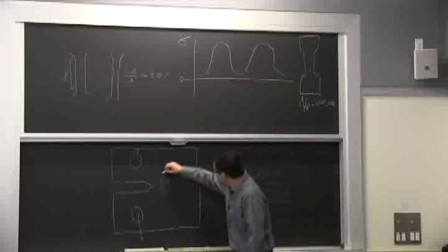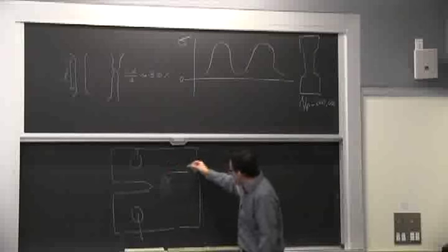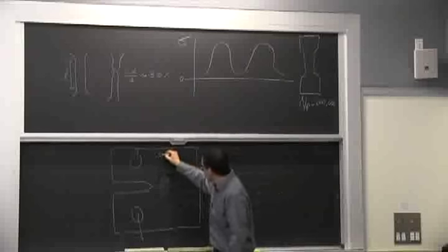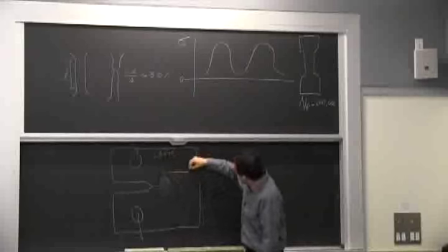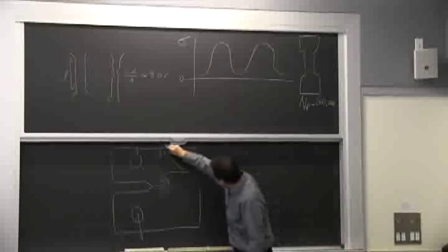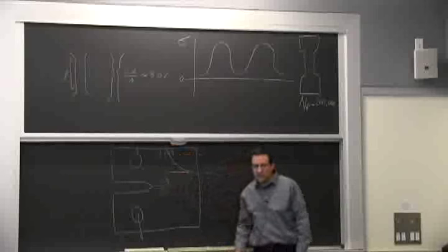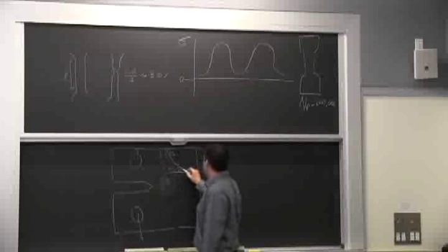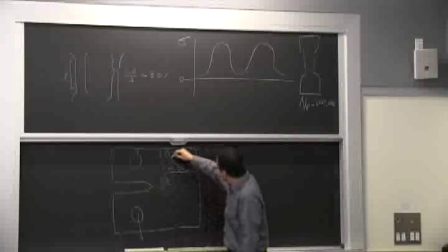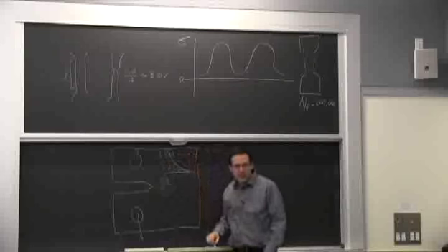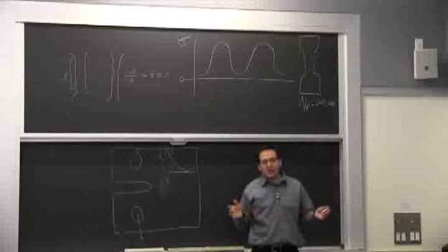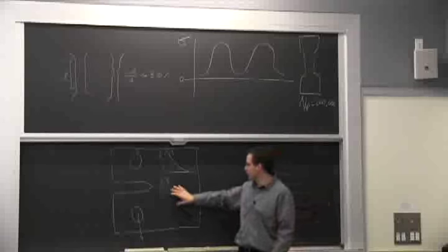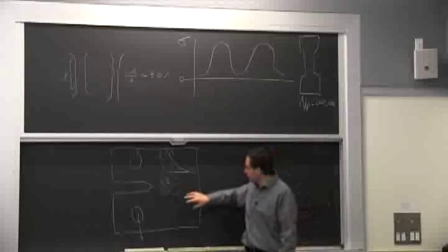Well, the stress field that I assume, and we're going to call this linear elastic fracture mechanics, that's K. Our stress is supposed to go to infinity, but in reality, it stops here. If our actual stress is assumed to be that way, in reality it's probably going to be like this, and it's not precise anymore because our plastic zone is not small as opposed to the overall sample.